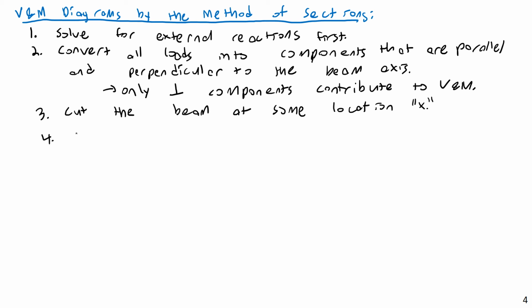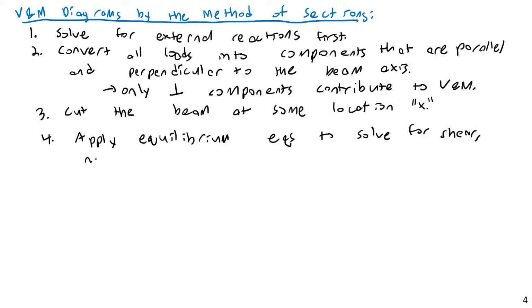And then 4, apply equilibrium equations to solve for your shear and moment. And I suppose if you wish, you could also do axial force. Shear, moment, and axial force.